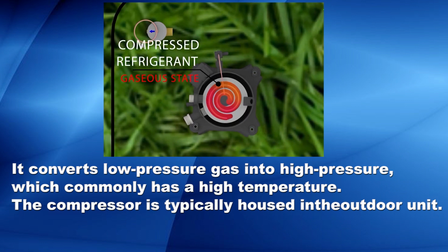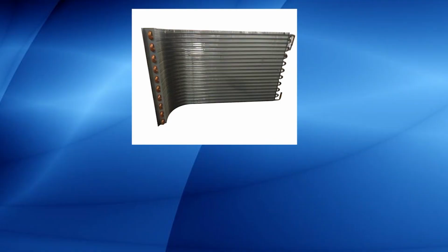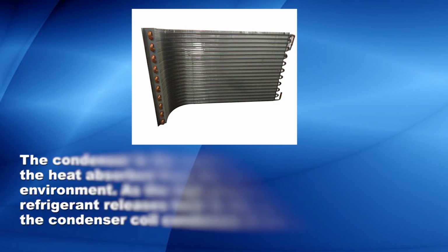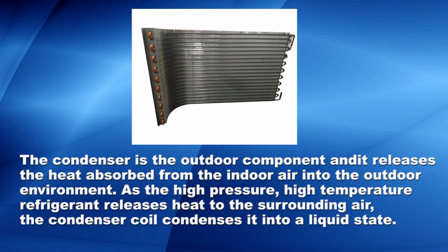The compressor is typically housed in the outdoor unit. The next component is the condenser. The condenser is also an outdoor component and it releases the heat absorbed from the indoor air into the outdoor environment. As the high pressure, high temperature refrigerant releases heat to the surrounding air, the condenser coil condenses it into a liquid state.